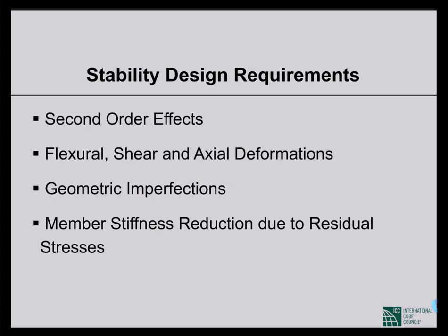But if we want to consider these geometric imperfections, we have to go for nonlinear analysis. And they also hasten the buckling. So geometric imperfections are important. We'll discuss a little bit about that in the direct analysis method, DM, which I will try to cover tomorrow. So today we'll cover the basic things. Basically, I think even to cover basic things, it will take a long time.